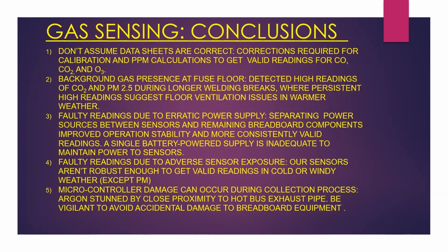And finally, we did sustain some microcontroller damage that occurred during the collection process when I stunned the Arduino because I got it too close to the hot exhaust tailpipe that was illustrated in the demo. So the advice there is to be vigilant and to avoid accidental damage to breadboard equipment while you're trying to collect gases.